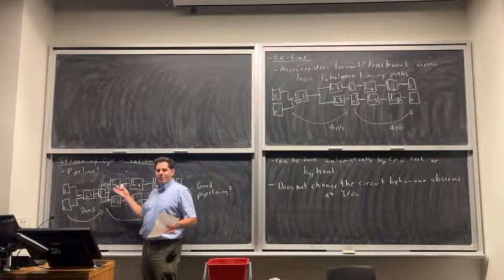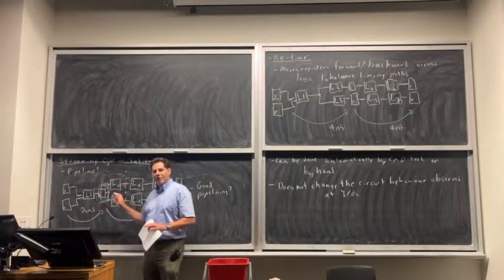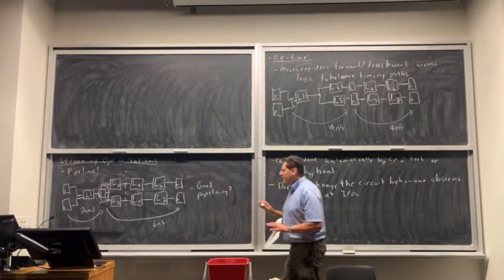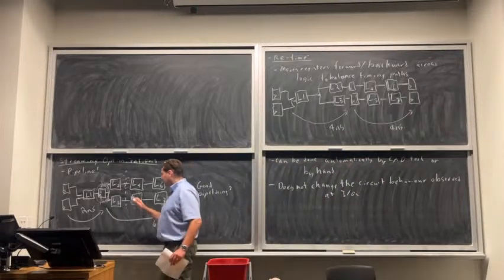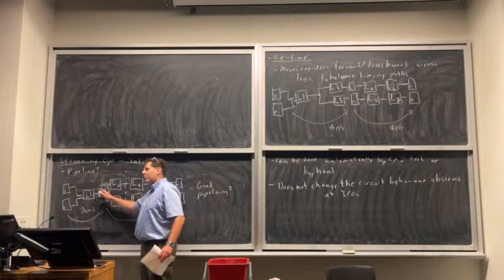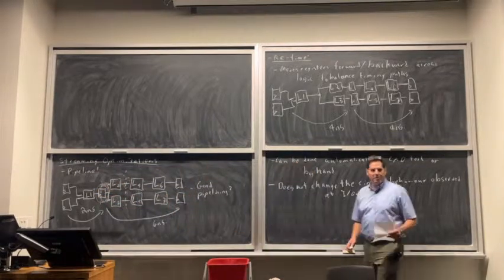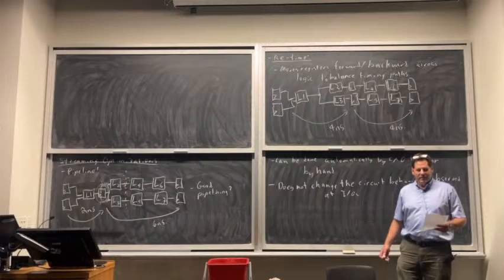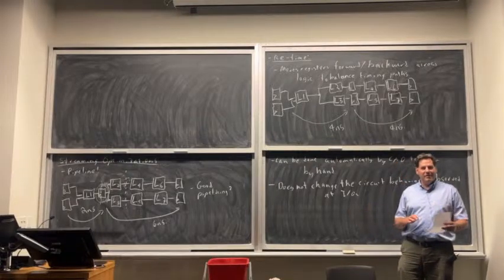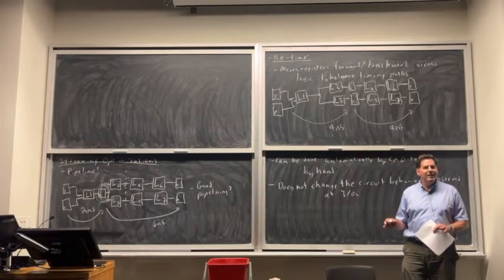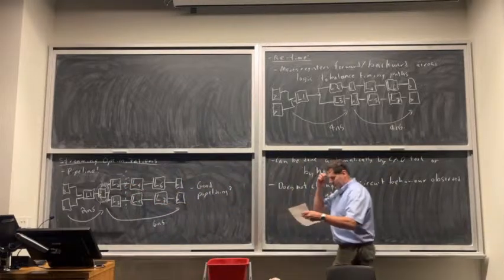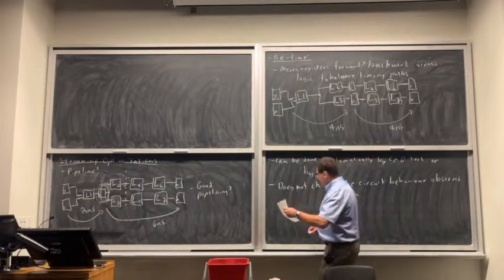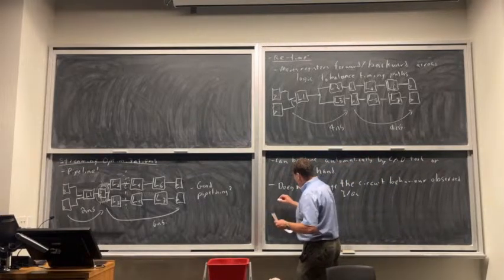So you can leave retiming on certainly for the final compiles when everything's working. Maybe you'll never have a problem in hardware that didn't show up in simulation, in which case it's fine. If you have a problem in hardware and are using those state debugging tools, you usually want to turn off retiming so that you can understand what's going on. Which also has some trade-offs. If it was a very subtle bug related to timing, then it's actually possible it goes away when you turn off retiming. But it is going to be a lot harder to interpret these registers when you read them back from hardware if you had retiming. Okay, so that's retiming. Another optimization.